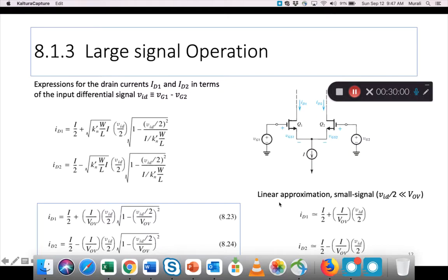That means the output waveform, if it must be similar to the input waveform, just of higher magnitude and no other changes, no other distortions, for that to happen, you need linearity, right? That's the definition of linearity. The output is similar to the input, only difference is the magnitude is different. So for that to happen, it's possible even in here, even with all these square formulas, still possible to make it linear, assuming your input signal is small.